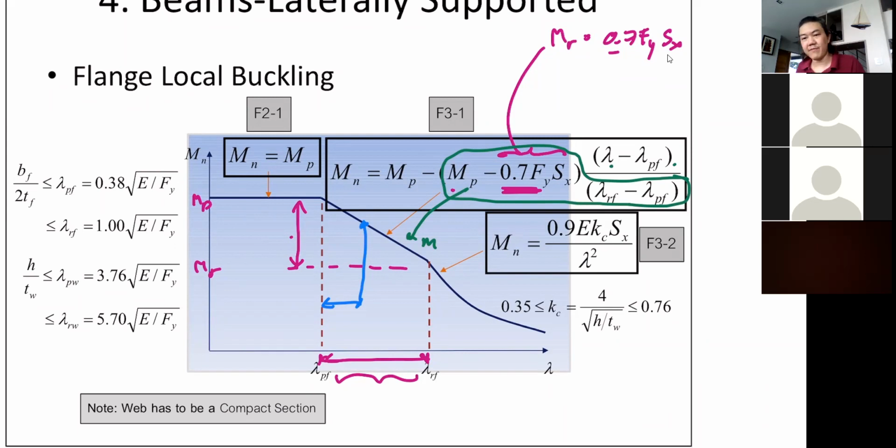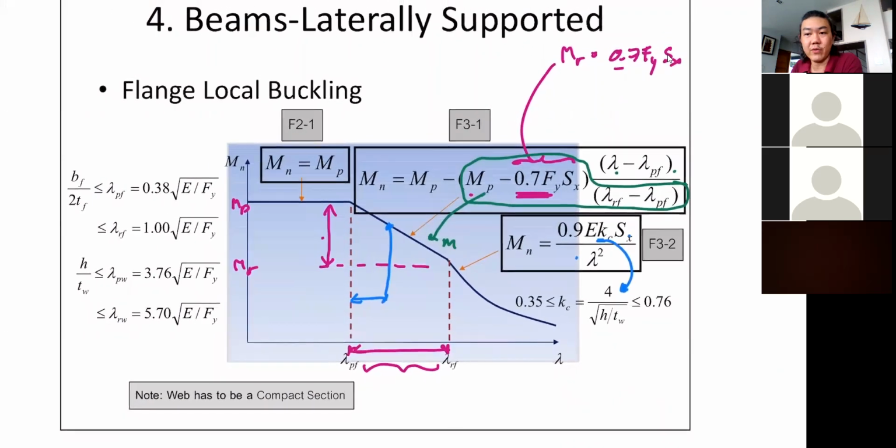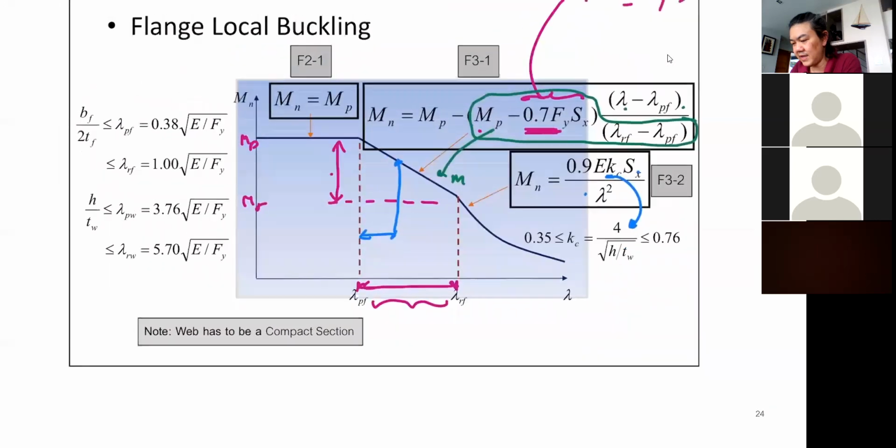Okay. And when your flange becomes slender, which I already told you, we don't have the slender flange. So when you calculate something and then you find, wow, my flange is slender, you must be aware something could be wrong. Now, this is the classical solution as well, coming from mathematics. Kc is this thing, this guy, okay? And then you need to use the elastic section modulus, lambda squared. So that's the whole picture of the local buckling of your beam. And then for the global buckling, it's just Mp, okay? So I think that's it for the session here now, okay?